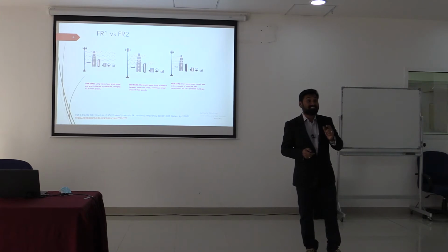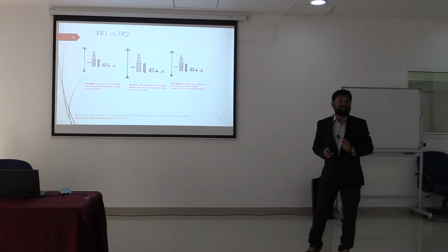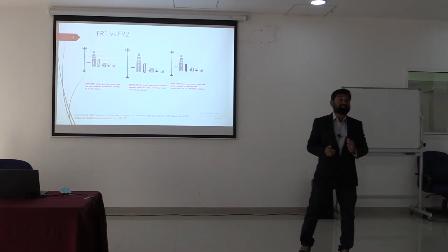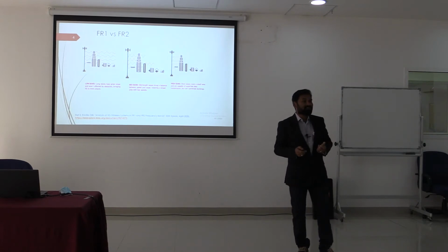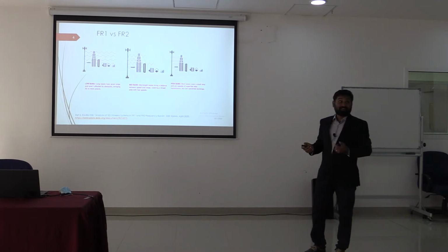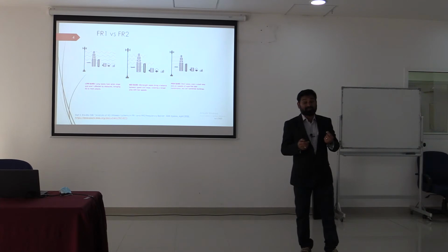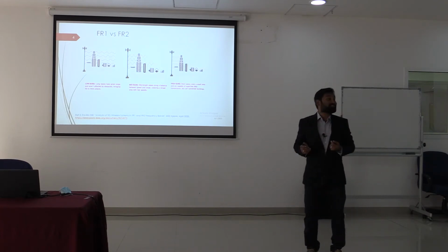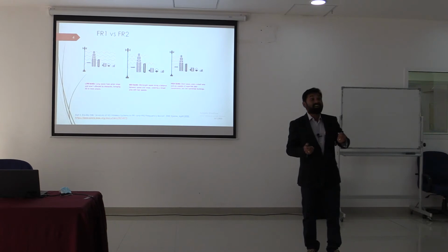But the advantage is that in the millimeter wave spectrum the bandwidth is very high, so you can get super fast data transmission. So throughput is maximum. In the meantime, your coverage area becomes limited. Therefore, it suits local applications like an industrial environment, the agriculture field, or smart homes and smart applications, where coverage doesn't matter and only the data rate plays a vital role. So for those applications, 5G plays a vital role with millimeter wave. It is not suitable for wide coverage applications like cellular mobile.